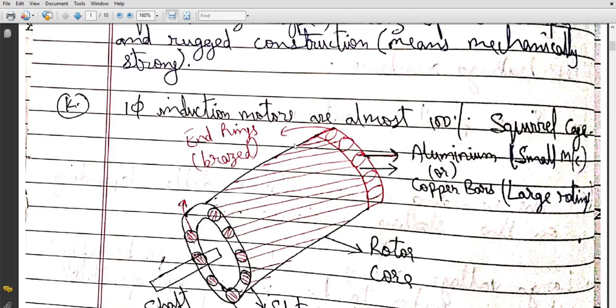If now the number of stator poles is reduced to 2, then automatically this rotor structure will be reduced to 2, meaning the rotor will now carry 2 poles. If stator poles are 8, then rotor poles will automatically be 8. You don't have to do anything. Now how is it done? How does this rotor develop an equal number of poles as are present in the stator?